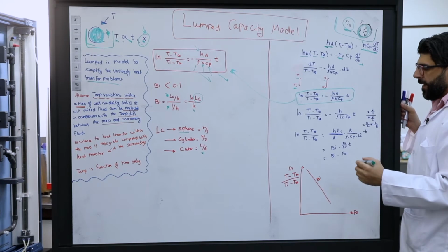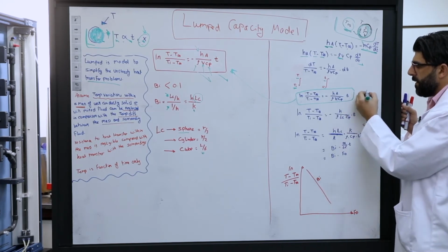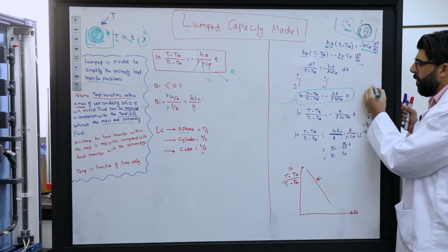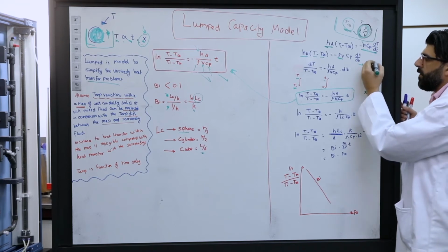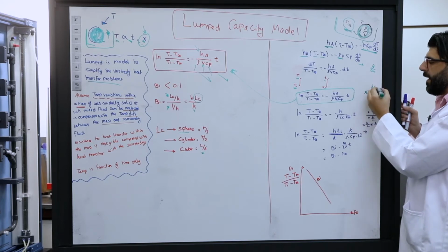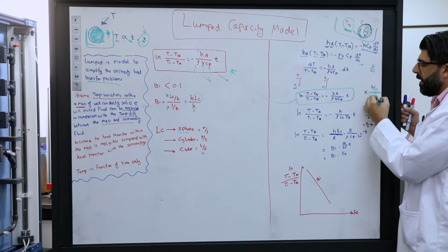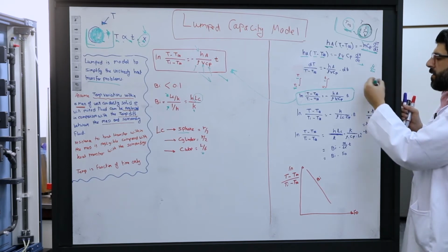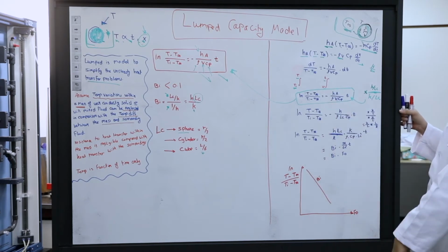I can multiply this equation by k over L, this is the conduction, k over L, because as you know the conductance is k over delta x. So it will be k over Lc, the characteristic length, overall k over Lc again, so it will be 1. If we add it here, it will not affect the balance of the equation.